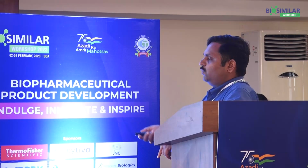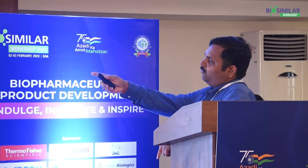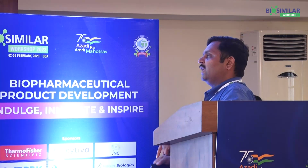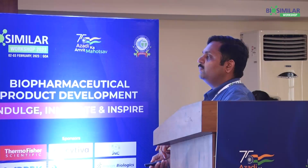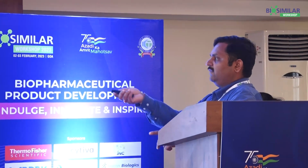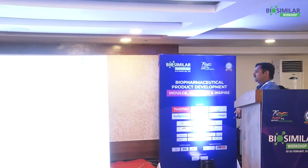For this, we need to know how much time it will take to achieve the breakthrough, which is denoted as S. And definitely the flow rate is important because these 2 parameters help calculate the productivity and capacity utilization. Productivity, as we coin the term, is the total protein purified per unit of time and resin volume.